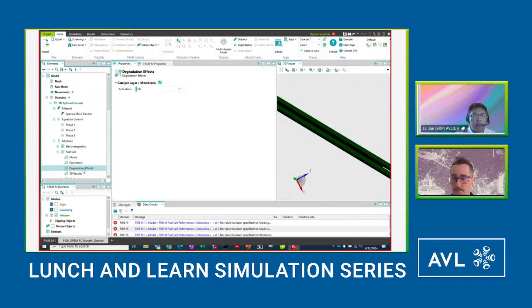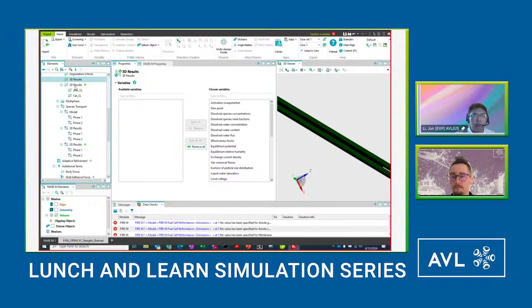And then we have the degradation effect. Here in this case it is not activated, but if they're interested, the user can activate the degradation effect, either for steady state to look at the membrane degradation, or with a transient simulation, to look at other things like catalyst layer degradation in cycle conditions. And then we can specify the 3D and 2D results output.